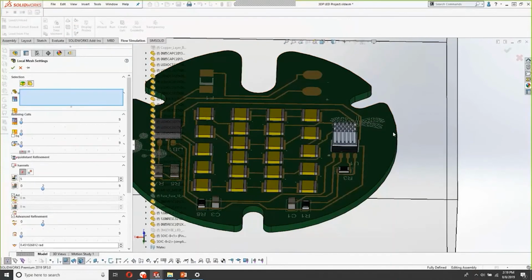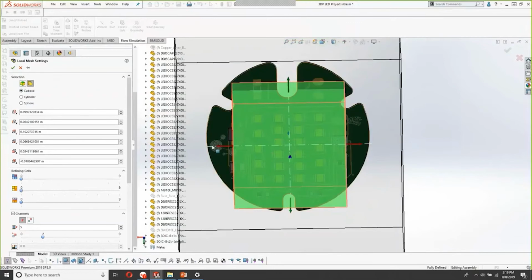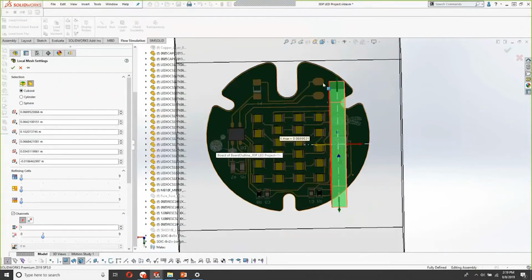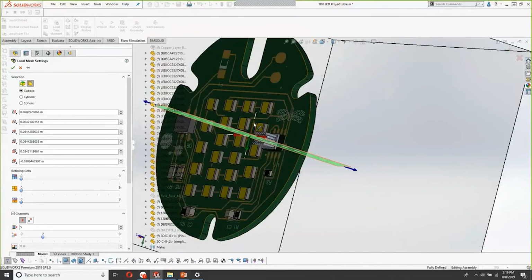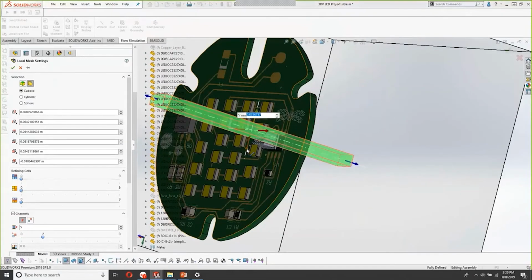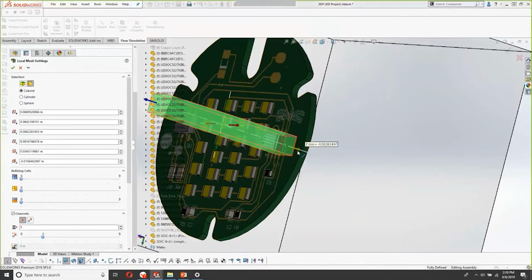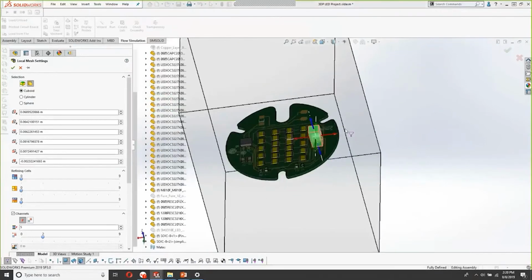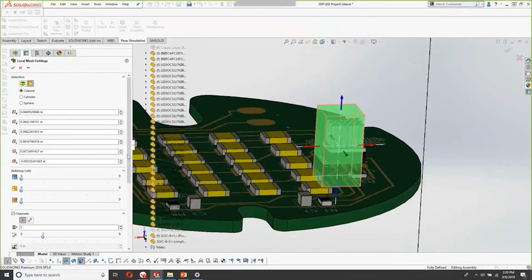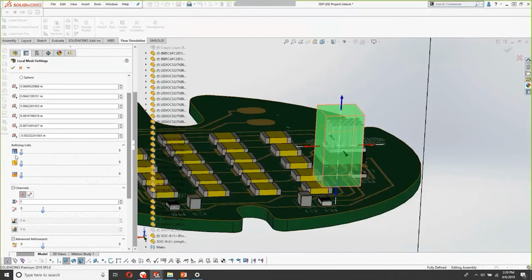I can just, much like the computational domain, push some arrows around to get a tighter mesh in the area where I want it and not worry about it so much in the area that I don't. What this will do is allow me to say how many times it can break that square, or that cube, into smaller pieces. And we'll say 3 for fluid, solid, and at the interface between the two.